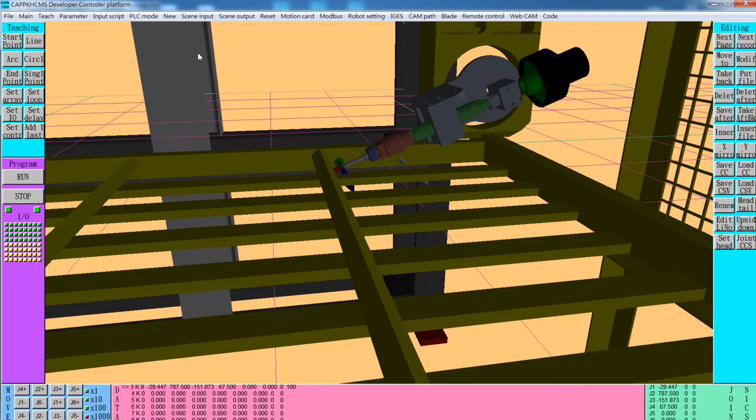100 millimeters per second. Then the third point is created, we can run and use visual to see the script. It seems okay. Then we have to add something at the front and the rear to lower the tool vertically and incline it in. How to do it? We just use head, move to the index of the first line, and use insert to insert one line.